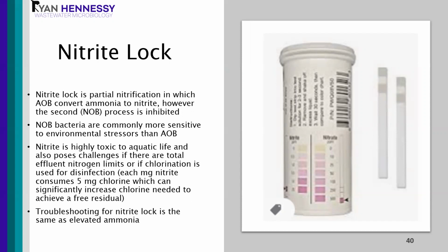Nitrite's also highly toxic to aquatic life, and if you have disinfection through chlorination, every part per million of nitrite is going to require 5 parts chlorine before you're able to get that residual. So just a very small amount of nitrite can really pose challenges with disinfection and meeting limits like fecal limits, things along those lines.